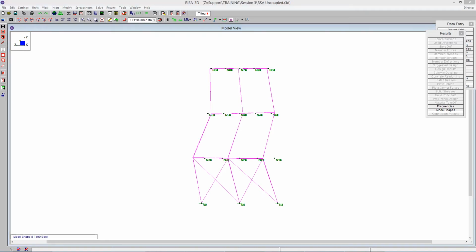So the power of this is that we can go ahead and combine all of those together to get a dynamic analysis for the entire structure. And ASCE 7 is going to require that whenever you have a case where the equivalent lateral force method is not going to give you this type of single dominant mode shape that you can just assume and go with. So we're going to actually take more of a fine-tuned approach and look at this in each mode shape and then sum it together.